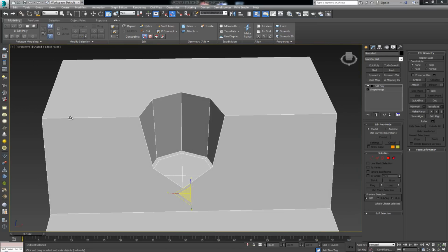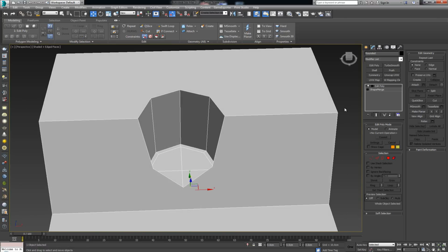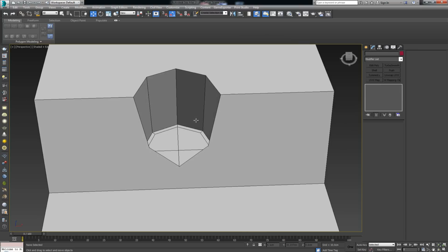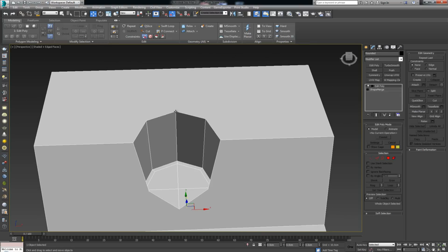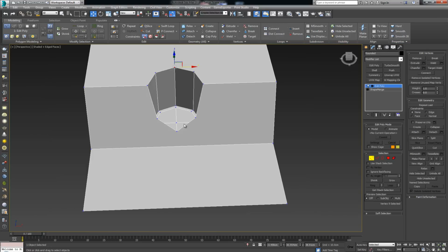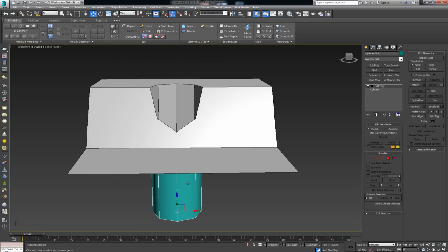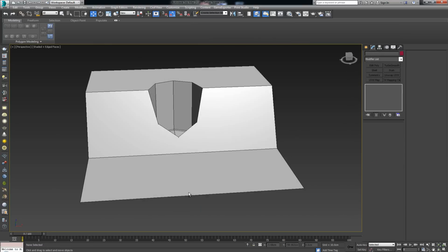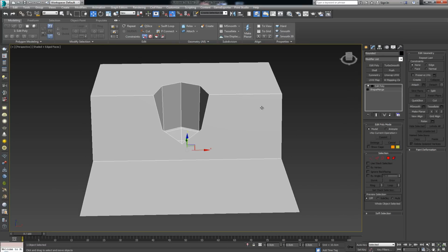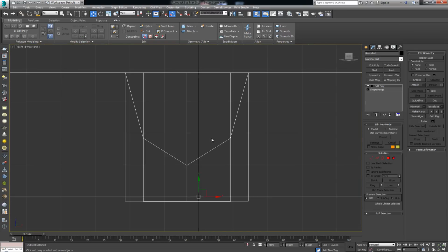Since we already have this portion centered out, we need to have one more main line, which would be this one over here. Now, we can do this by going ahead and cutting here with the cut tool and going down here as well, but I want to show you another way, or a quicker way. I'm just going to delete this because I no longer need it. And that is, I'm going to select this. I'm going to skip over to my front viewport like this.